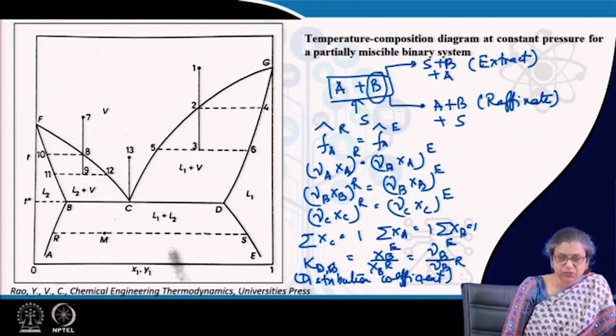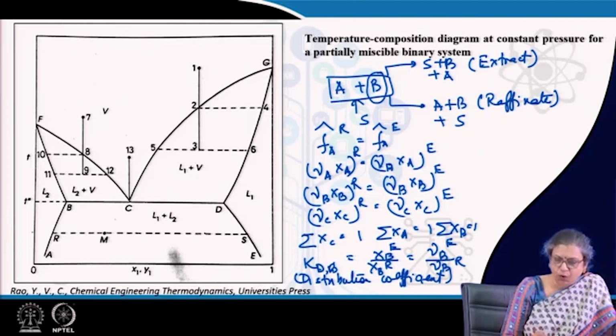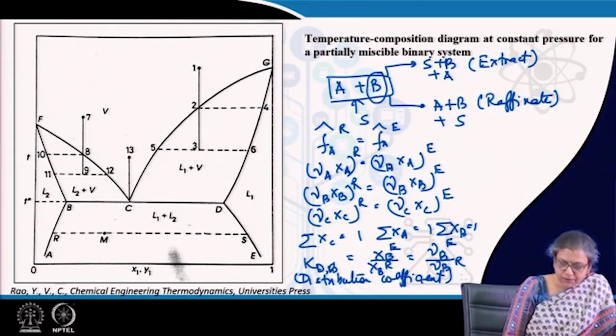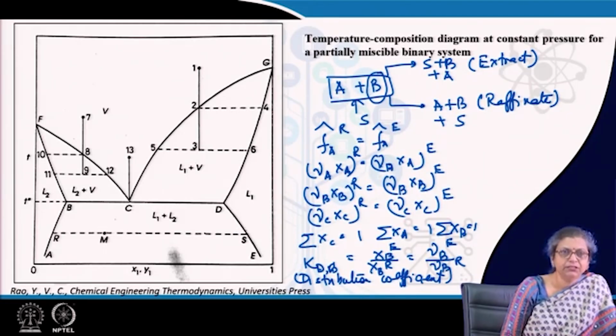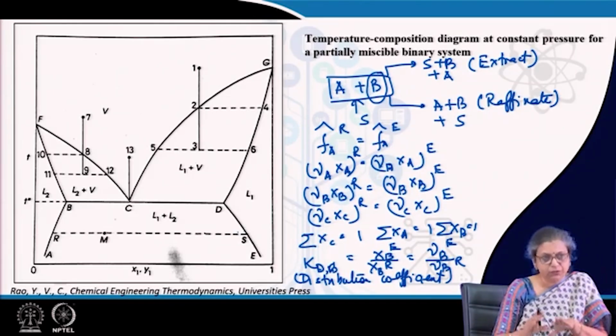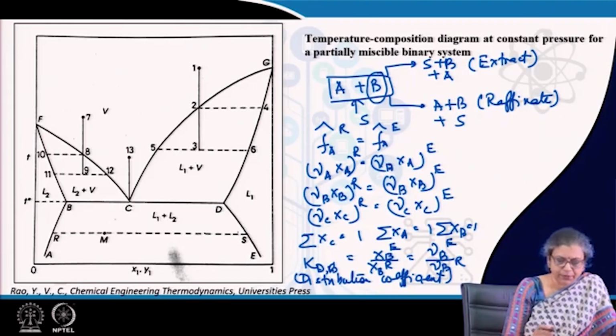Over some particular range, say, we start with pure liquid L2 and then start adding L1 there. Gradually we find that there is one particular zone where the Gibbs free energy of the solution is higher than the Gibbs free energy of the two components taken separately.